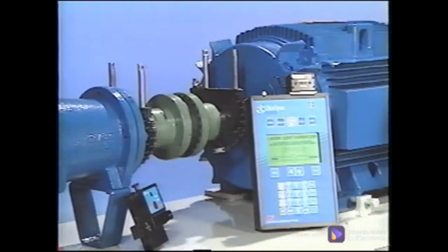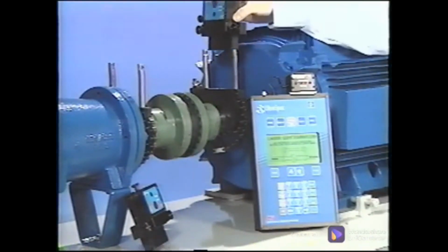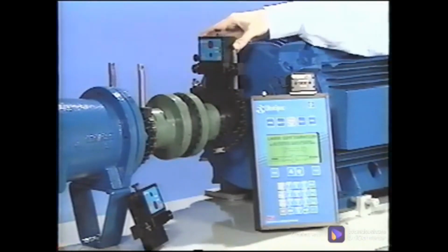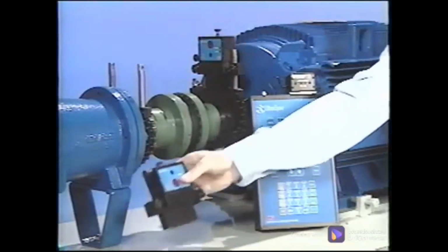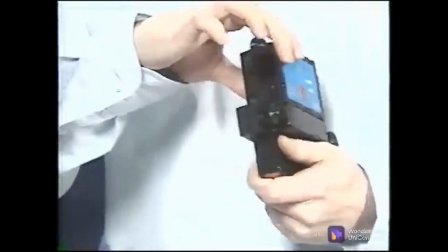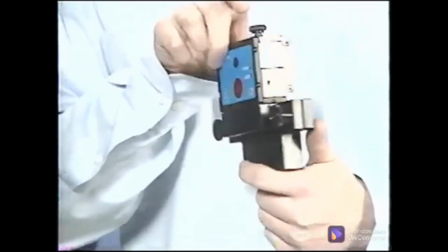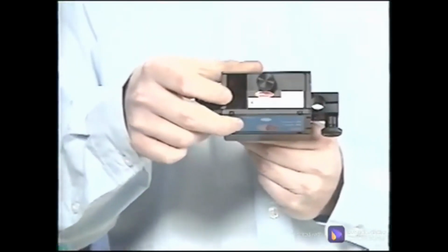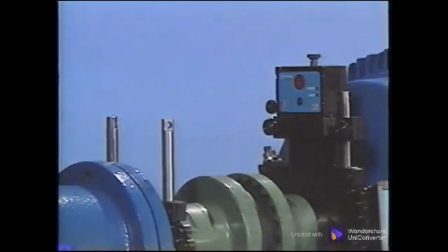The laser system setup is very similar to the electromechanical system. Mount the brackets in the same way. The laser heads are different than the electromechanical heads in that they use wireless communication through 3 infrared ports to talk to the analyzer. 2 ports are on the sides and 1 port is on top. Each head has a visible laser beam and target.